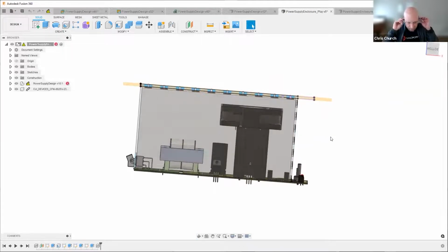So this is where our typical design for manufacturability team would come in and give this feedback. We have two options, right? Depending on what you want to do here, we could run those screws down through the top, leaving some pan heads exposed, and use nuts on the bottom of that fan and some thread locker to hold it in place, because we'll always use thread locker because vibration happens, even if you don't think it'll happen. But that's going to leave these kind of exposed threads.